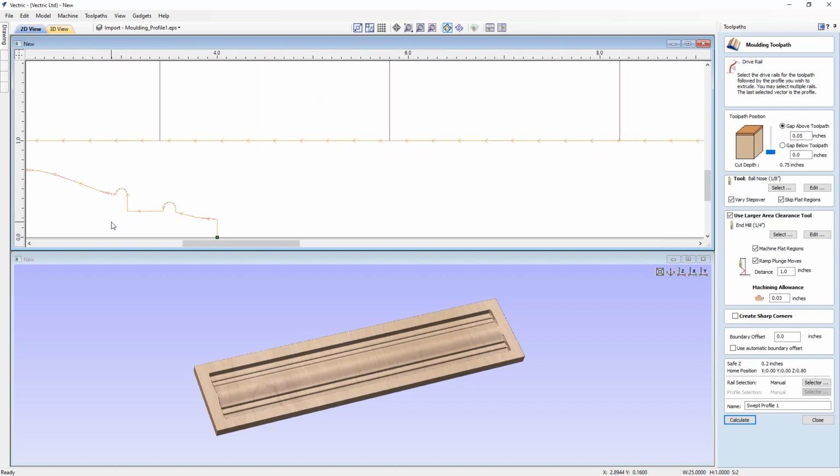So right now, when we cut this, we're actually stopping at the edge of our profile, but never dropping off the side of it. So right here on the top, the height here is the thickness out here on the side of your molding. Now, if we decide on a boundary offset, because we actually want to overshoot that a little bit, let's type in 0.2 of an inch.